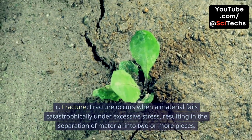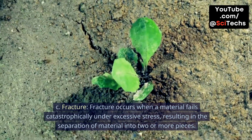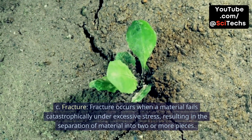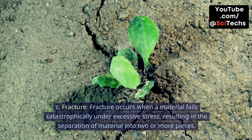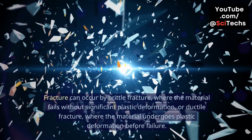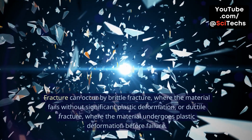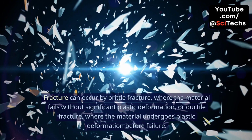C. Fracture. Fracture occurs when a material fails catastrophically under excessive stress, resulting in the separation of material into two or more pieces. Fracture can occur by brittle fracture, where the material fails without significant plastic deformation, or ductile fracture, where the material undergoes plastic deformation before failure.